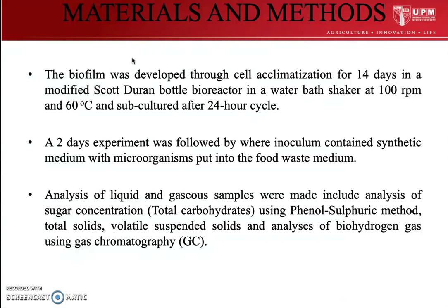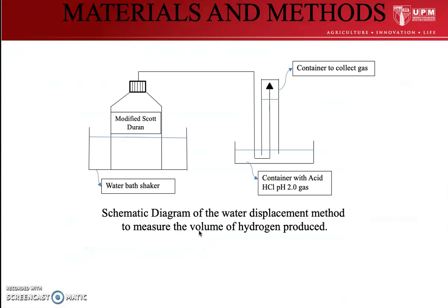The 2 days experiment was conducted using the inoculum that we get from this part, and then liquid and gaseous samples were taken, which included analysis of sugar concentration, TC, by using the phenol sulfuric method, TS and VSS, and analysis of biohydrogen gas using gas chromatography, GC. So this is the schematic diagram of the water displacement method to measure the volume of hydrogen produced.